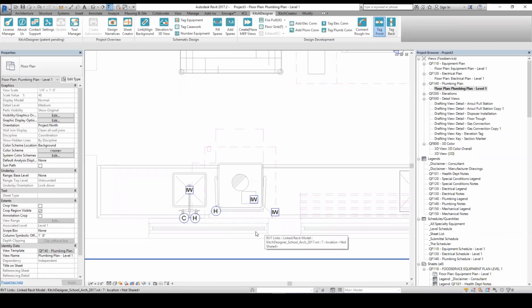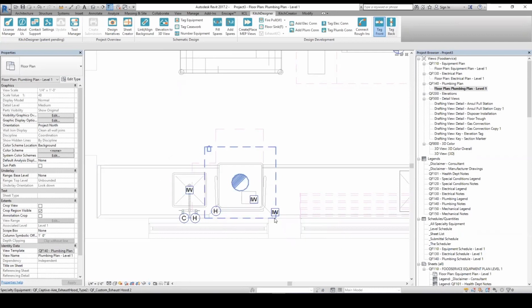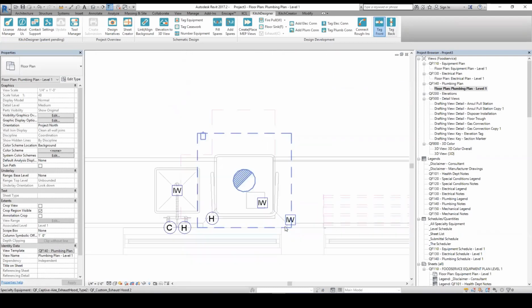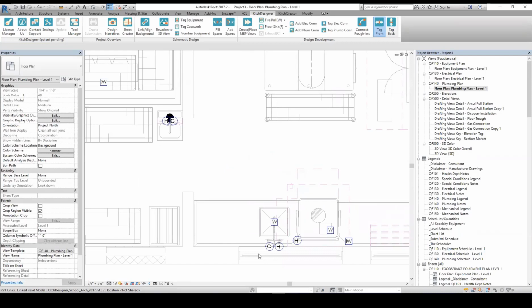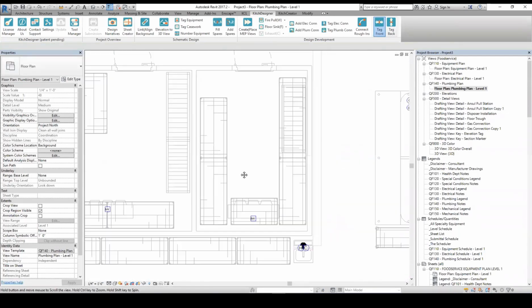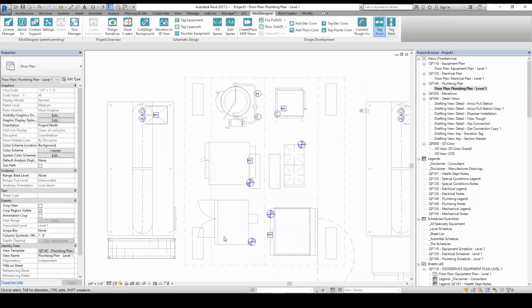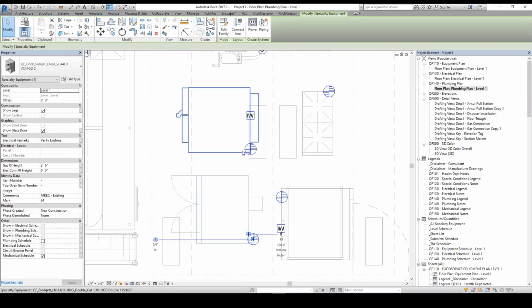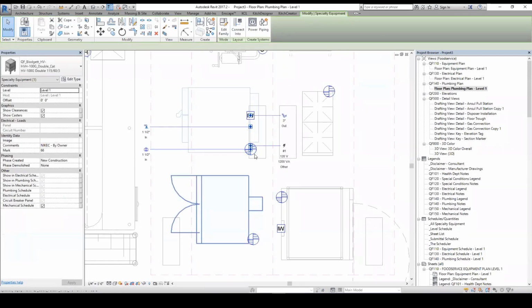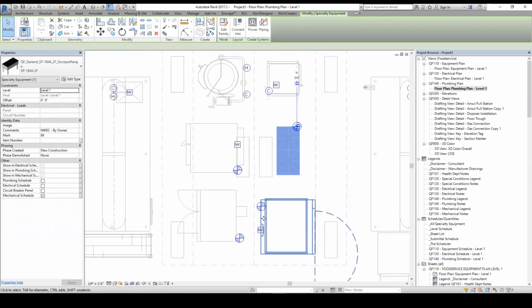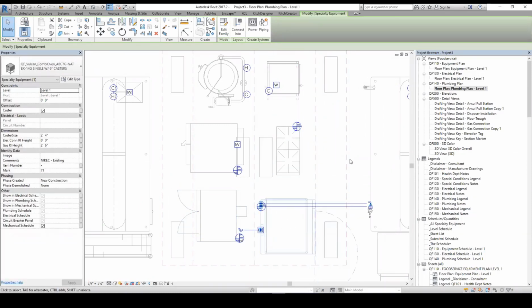And for the most part, everything is in pretty great places. Not much we need to touch. It's great to see the indirect waste coming out where they actually come out. It'd be really helpful when we place floor sinks to know where the drains are leaving these pieces of equipment. Evaporators, another hand sink. Here's some cook lines. Here's these gas locations. So this used the connector here. This looks like this used the connector for the location. Same thing with this stock pot. Same thing with this combi oven.